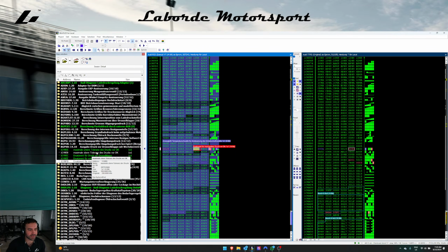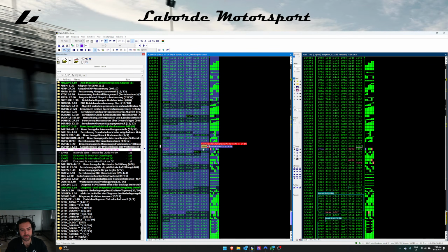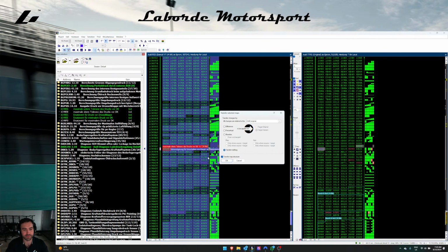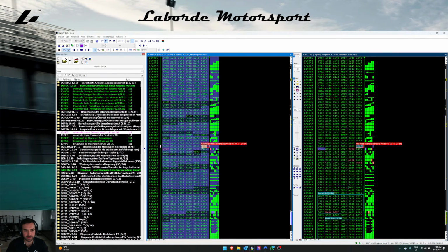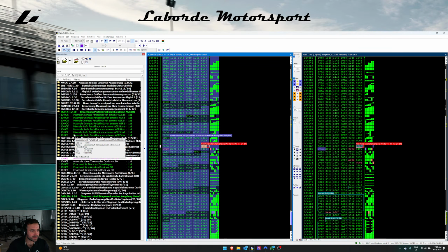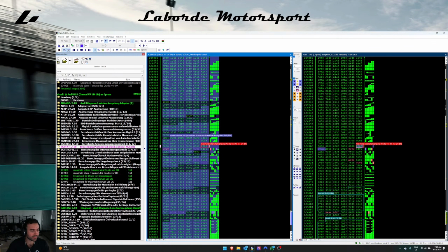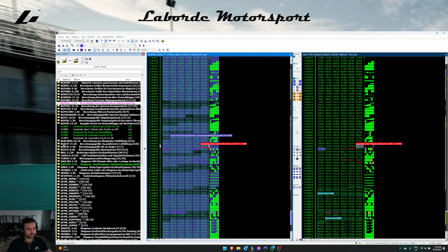Like I said before, I'm going to find a few of the maps that I need, the minimum and maximum tolerances for pressure before the throttle. And then I'm going to search through a few more maps that are going to allow us to achieve this lack of throttle closure, I suppose you could say.